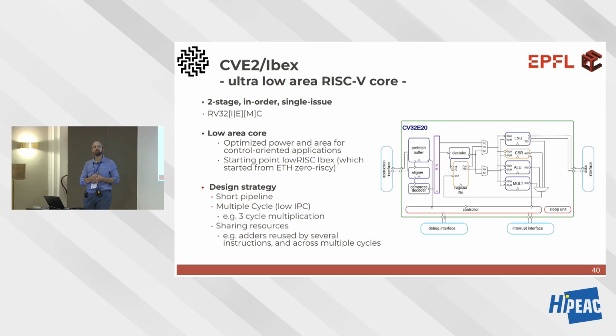As your colleague suggested, RISC-V defines some opcodes that can be used for custom extensions. Those will never be touched. But once you decide what your ISA is in your CPU, you can use whatever bits to implement your custom extensions. Of course, you don't have to collide with whatever else you're implementing there. That needs to be compliant with RISC-V if you call your core RISC-V. But then you can use the remaining bits to do whatever you like. If the custom space is not big enough for you, you can use also the rest. But I would say it's not standard. It's a bit hacky, but you can.